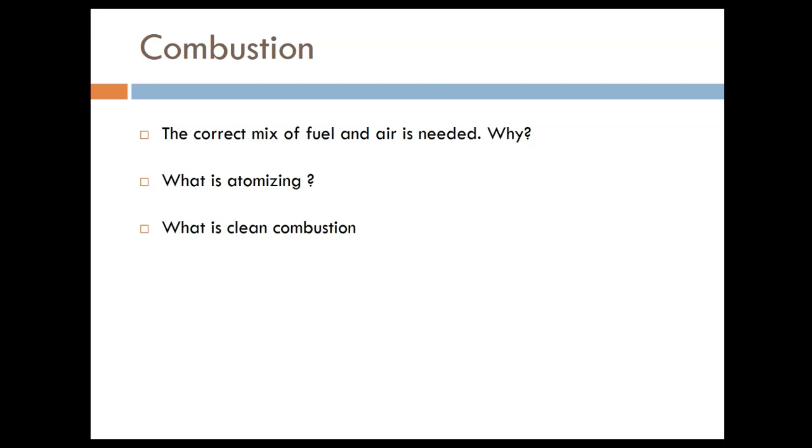For us to burn the oil properly, the oil has to be atomized. The word atomize means making something small, like an atom. It's actually changing the oil into vapor by pushing it through a small orifice. It's like a spray. That's a fancy way of saying spraying the oil, but it's more sophisticated than a spray. If you look at the oil, it's more of a mist, very small droplets. Clean combustion, then, is burning the entire fuel, no excess fuel, no smoke whatsoever.